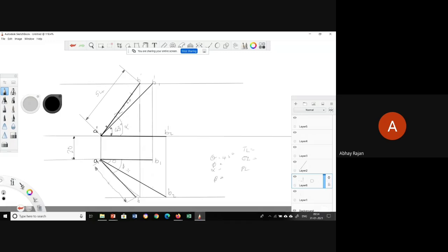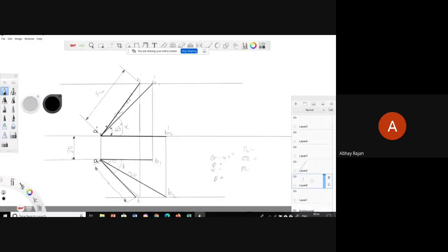So this can be labeled as true length, and the true length can be mentioned here, or you can write true length equal to right here itself. For that also dimension lines are required, like these lines. You can draw very thin lines so that it won't disturb our projection. See, our actual projections are in darker lines, right? These 3 lines in this set and 3 lines in this set, we have lettered these things properly. Similarly, we have dimensioned it properly and shown all the views properly.